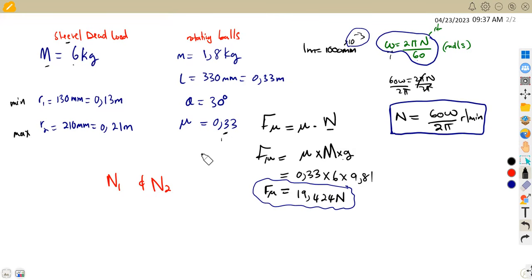That is, when we are given the frictional force, remember I said we can use this formula where we had the mass of the rotating balls plus the mass of the sleeve times gravitational acceleration, all this part being equivalent to the mass of the balls times omega squared times the height. So from this consideration, whenever there is a frictional force, take note, guys.